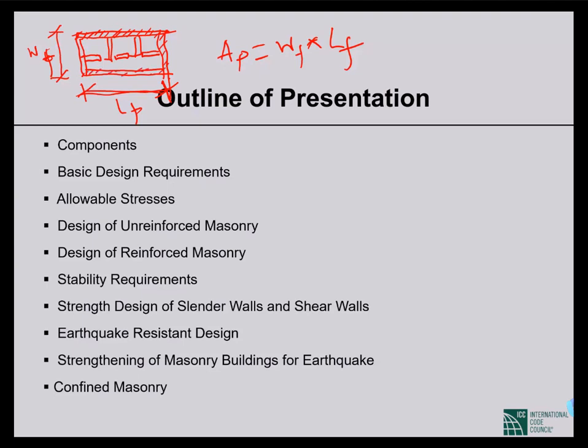Only the hatched portion. We are looking at a floor plan, and these are the walls. And the total summation of the wall area is say AW. Then wall density, say call it DW, is the area of wall divided by the total plan area. This is wall density.